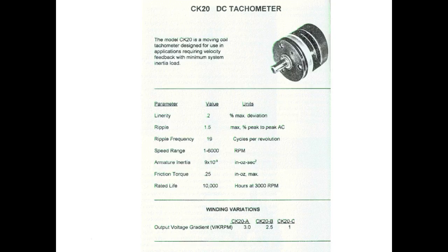So tachometers measure speed. That's what they do. So technically, any of these things I'm talking about, a speed sensor, could be technically called a what? Tachometer. It's just usually we call these tach generators because they generate a voltage proportional to their speed, right? You understand? And then we have optical tachometers, which would be the ones that we're fixing to do. So, okay.